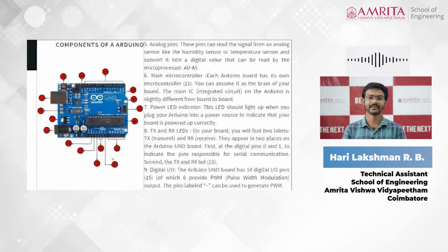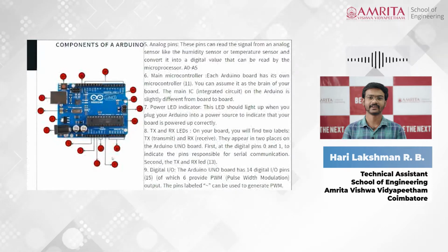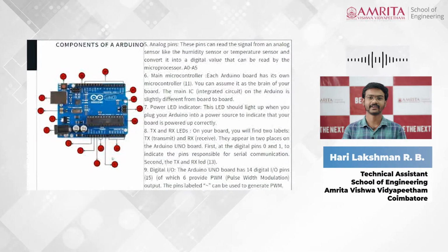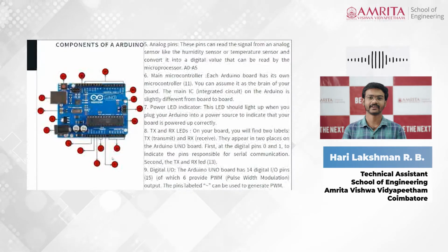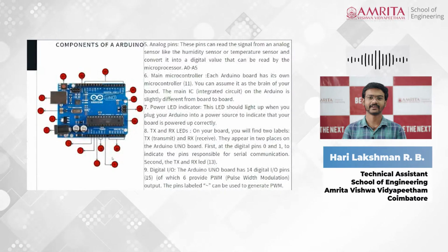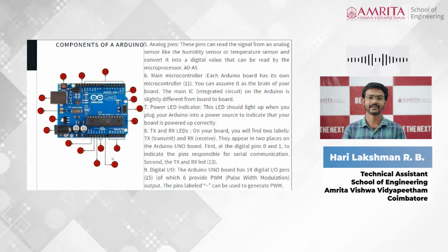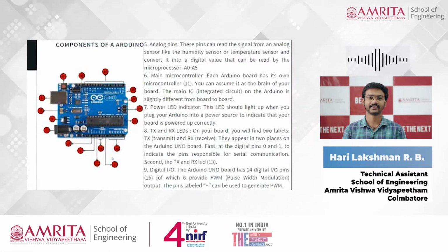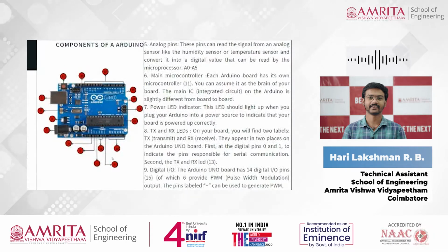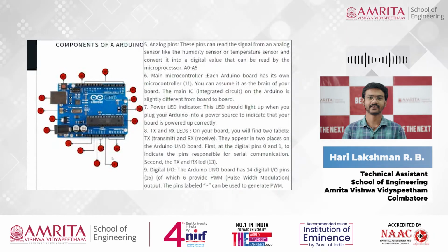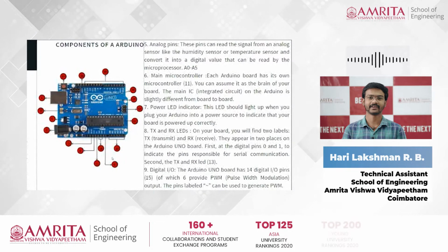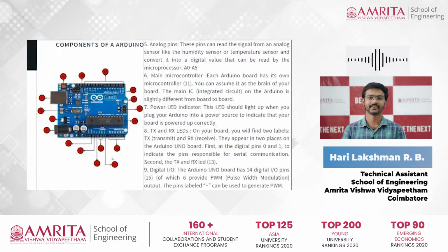Here we need to make a note that Arduino reads both analog and digital signals. But the output of a few sensors would be analog only. So those kinds of analog signals are taken from the pins A0 to A5, and the board converts the analog signal into a digital signal so that the microprocessor can read it properly.